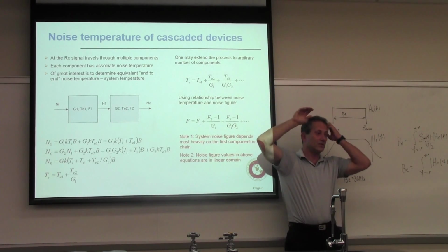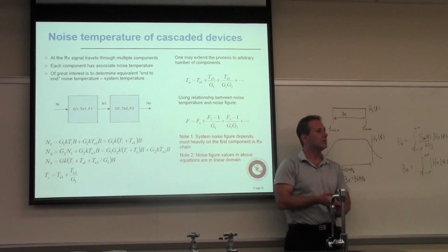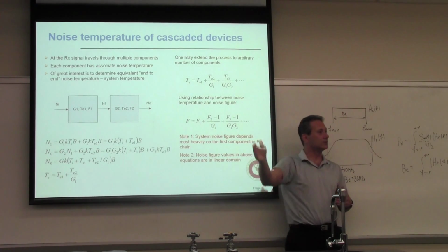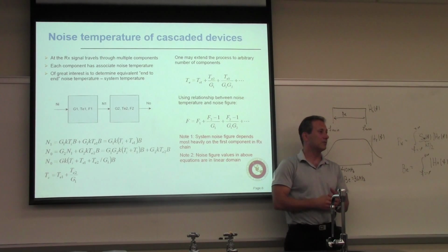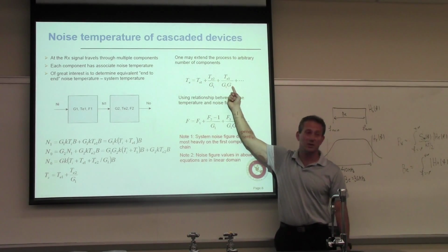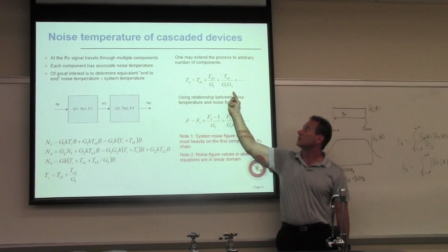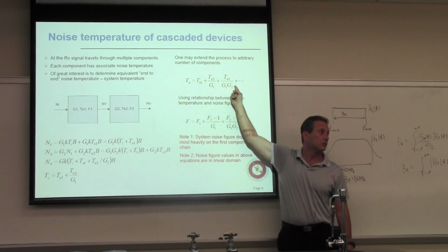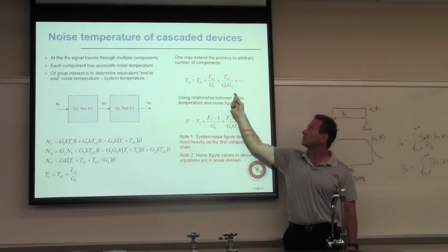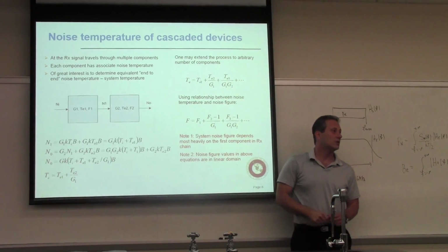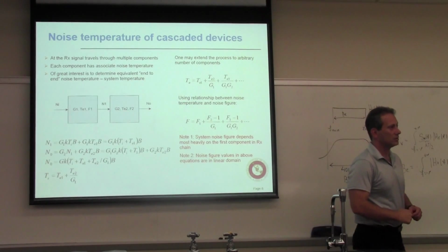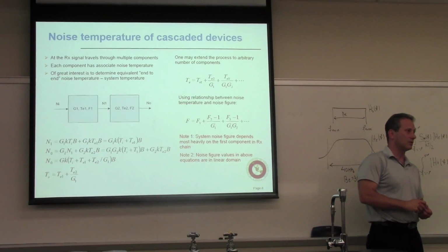Okay. So even if it's ideal in a sense that it implements the equations like they were coming from the book, half of the energy is going to be lost. So the mixers have a negative gain in dB, or a gain smaller than 1. The combination that usually appears here is the LNA gain times the mixer gain, and you're trying to make sure that this is not huge. Right? So this is large enough so that the noise figure of the mixer does not destroy the overall noise figure of the receiver.